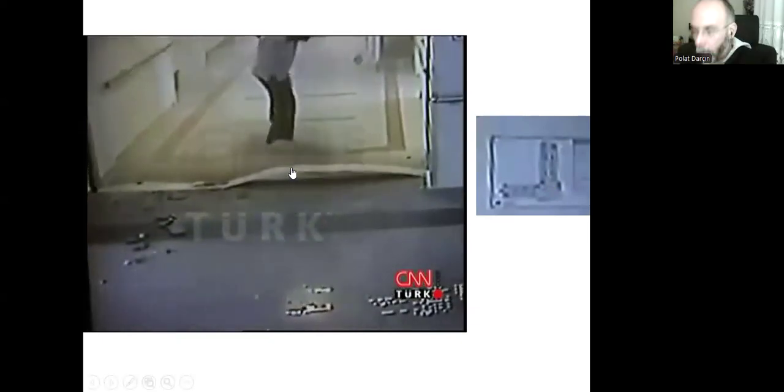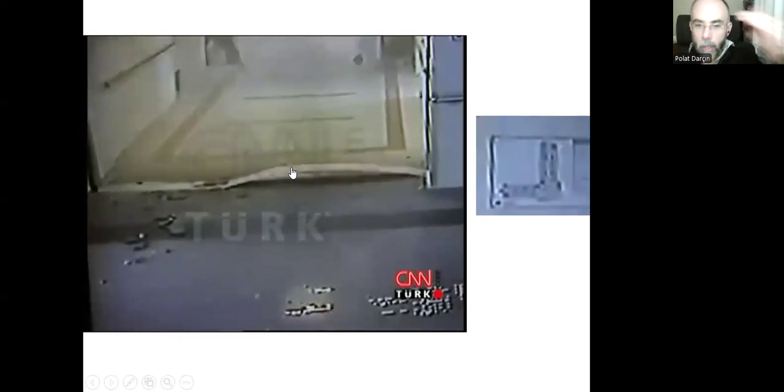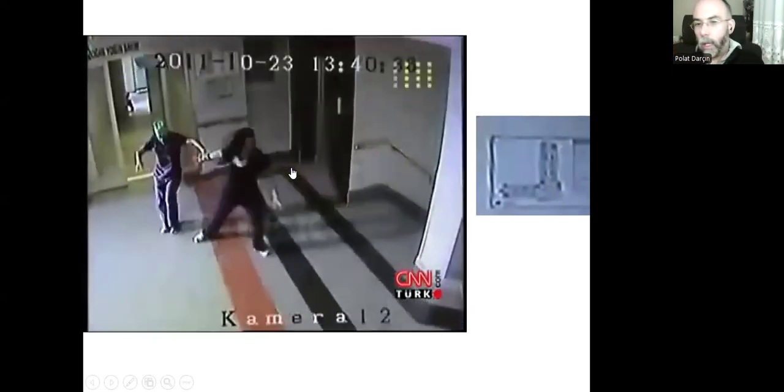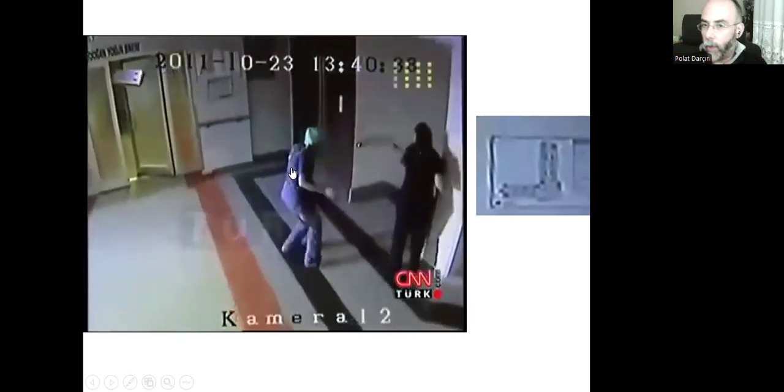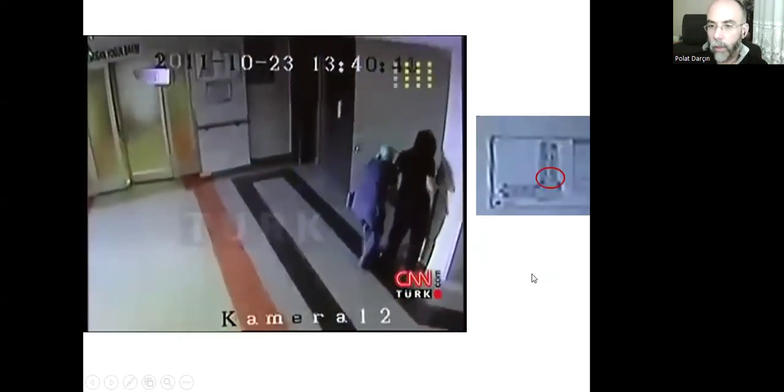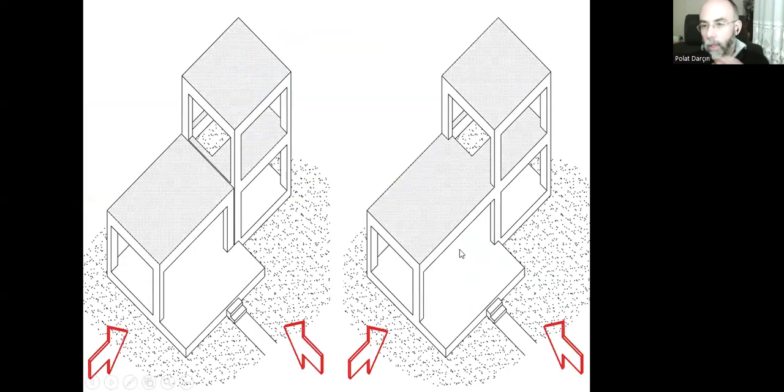That's good because with the seismic gap, what we call dilatation in Turkish, the structure will hold. That's the other solution. Instead of making the other part heavier so that we have a balanced structural system, we can separate the building.